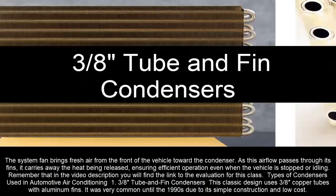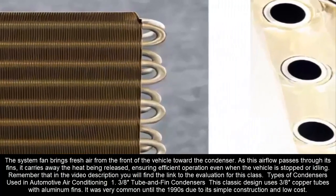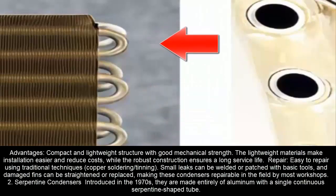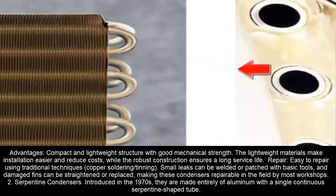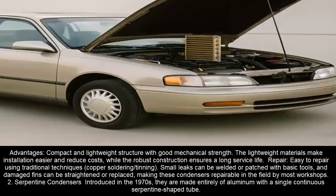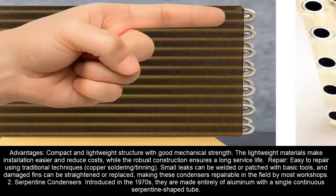Types of condensers used in automotive air conditioning. 1. 3/8-inch tube and fin condensers. This classic design uses 3/8-inch copper tubes with aluminum fins. It was very common until the 1990s due to its simple construction and low cost. Advantages: compact and lightweight structure with good mechanical strength. The lightweight materials make installation easier and reduce costs, while the robust construction ensures a long service life. Repair: easy to repair using traditional techniques, copper soldering or tinning. Small leaks can be welded or patched with basic tools, and damaged fins can be straightened or replaced, making these condensers repairable in the field by most workshops.